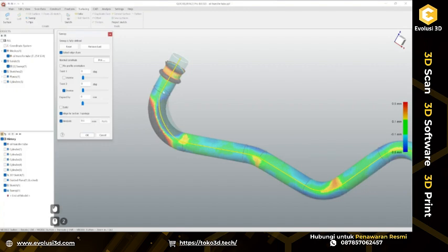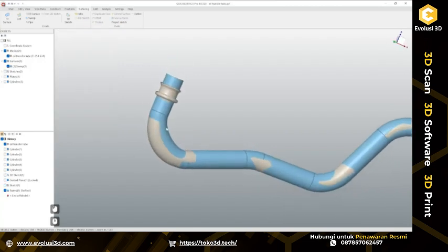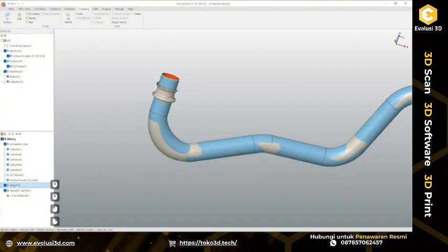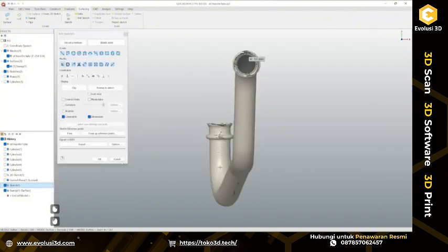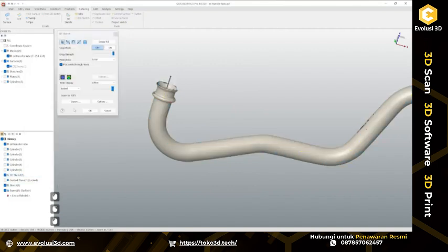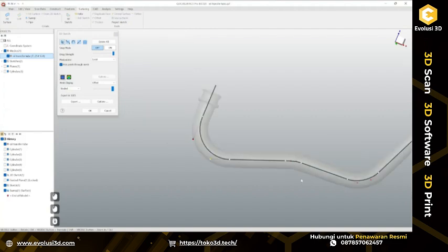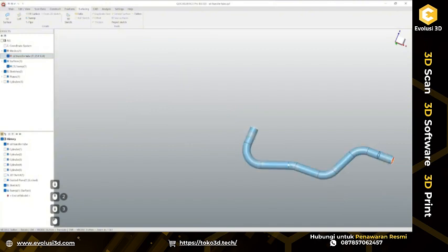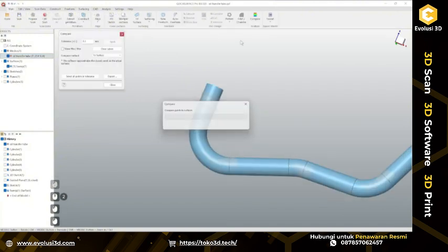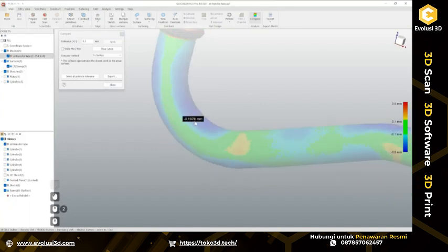Of course, at this point, I understand that I need to do some adjustments for those blend curves to match actual scan data better. Let's click OK, and now I'm going to edit. It's not this one. I'm going to edit 3D sketch. Let's make the mesh transparent so I can have better visibility here, and roughly just pull handles of blend curves to see how it changes and in which direction I have to go, more or less.